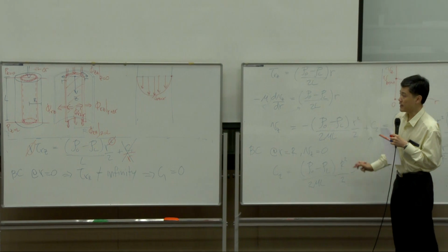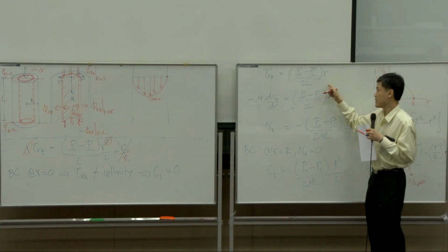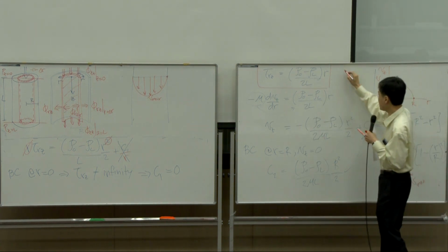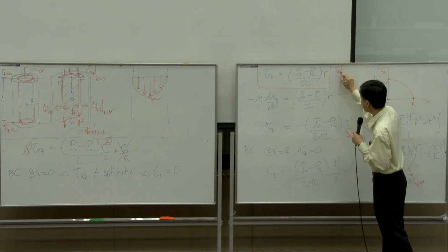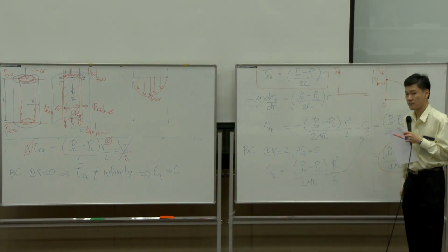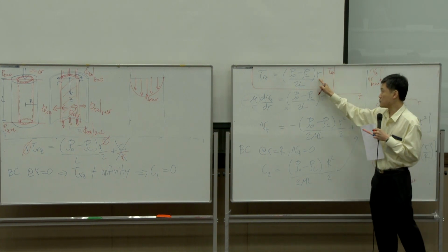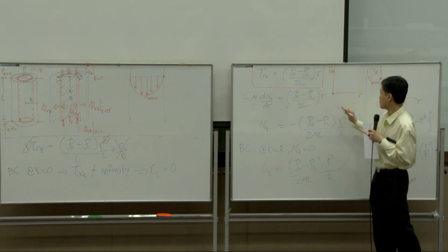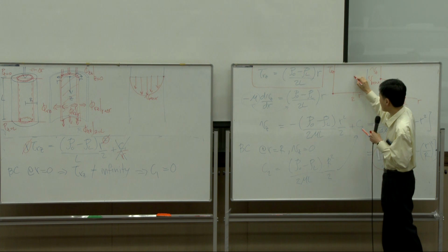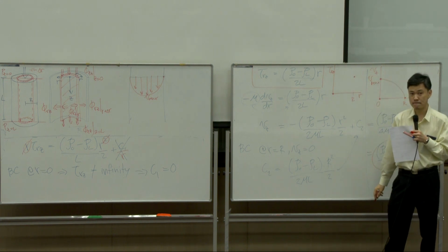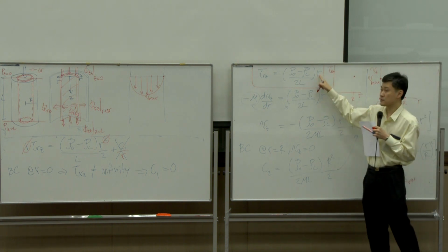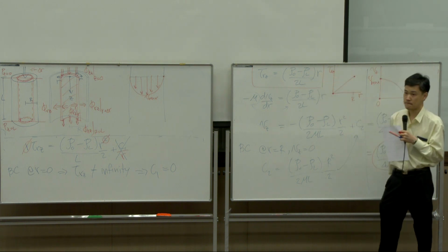Also, before we dismiss the class, this equation, which is the shear stress profile, if you plot between tau rz with respect to r, you get at r equal to 0, tau is 0. So it's 0 here. At r equal to capital R, tau is at its maximum, right? In between, it is linear because r is to the power 1. This is a linear function. So it looks like this.